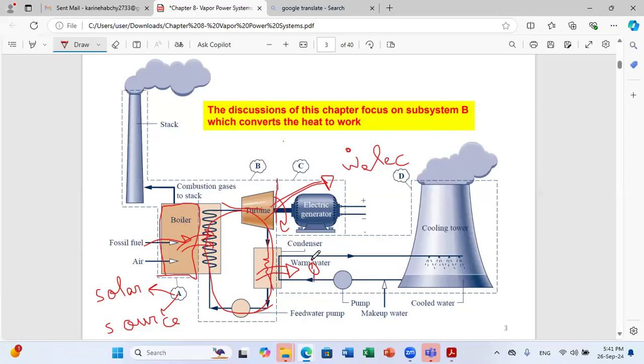In this case, you can go from vapor or nearly saturated vapor state to compressed liquid, because you need to go through your pump, which will increase the pressure again, so your fluid can enter the boiler. So this is the cycle in summary, the Rankine cycle, which is the part that we'll discuss a lot in this chapter.